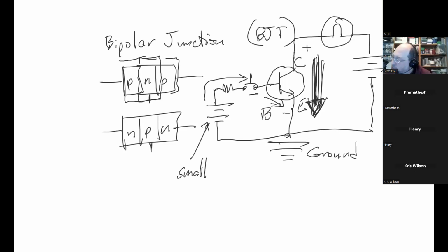And over here, we have a big power supply, and that's a big transistor, so that when we push this button down, it closes the circuit, which then basically opens up this big channel and allows a lot of current to flow from the battery through the light and down to ground. So what this basically does is this is a remotely operated switch.